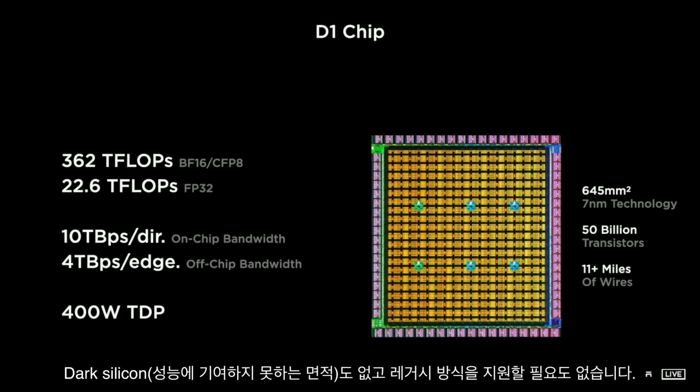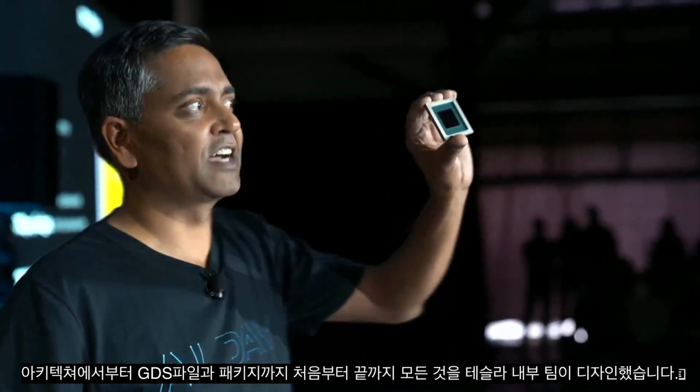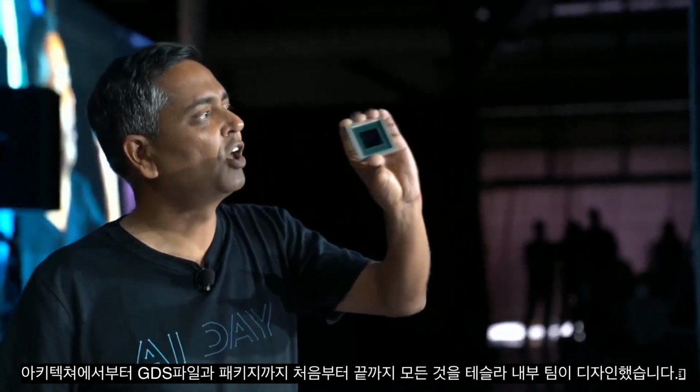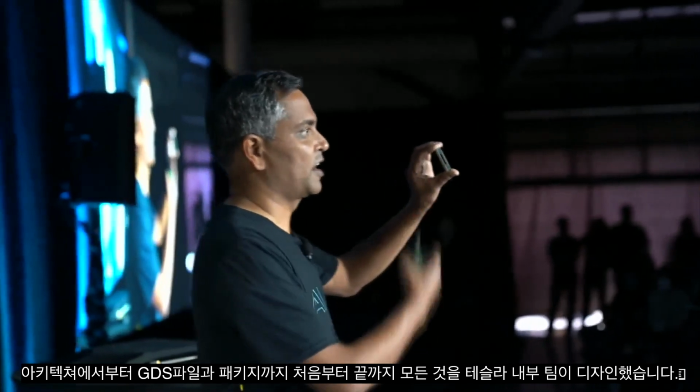There is no dark silicon, there is no legacy support. This is a pure machine learning machine. This is the D1 chip in a flip chip BGA package. This was entirely designed by Tesla team internally, all the way from the architecture to GDS out and package.